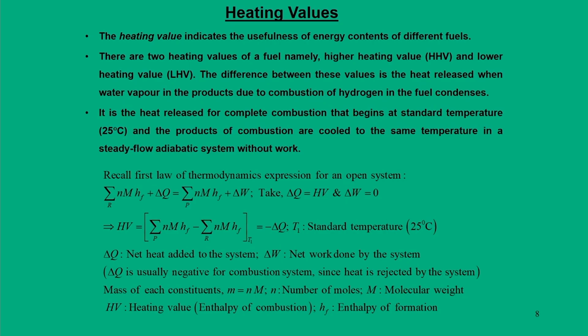Having said all these things, we are now in a position to define the heating value. Normally, the standard practice is not to define the fuel potential in terms of heat of combustion, rather fuel potential is defined by a common parameter, which we call the heating value. Normally there are two types of heating value that are interpreted, one is the higher heating value, the other is the lower heating value.